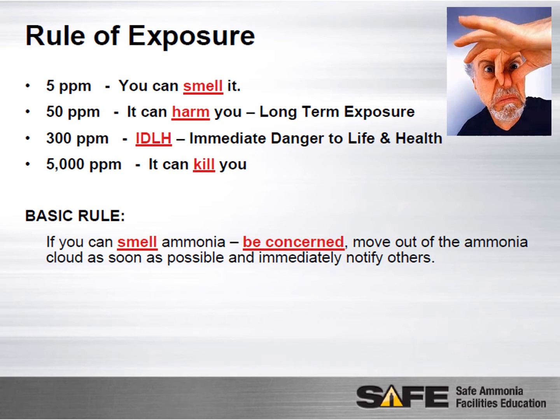At 300 ppm, it's an immediate danger to your life and health. That's what we were talking about on the previous slide, some of that coughing, lung damage, organ damage, skin burning sensation at that level. And at 5,000 ppm, it can kill you in a matter of minutes. So the basic rule is if you can smell ammonia, you need to be concerned. Move out of the ammonia cloud as soon as possible and immediately notify others.